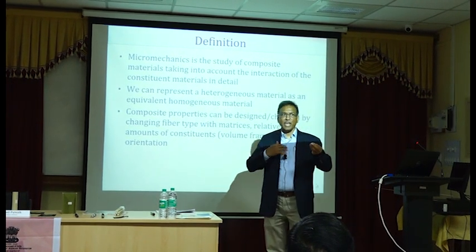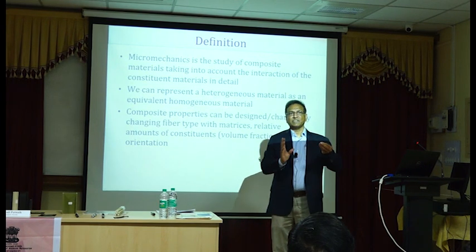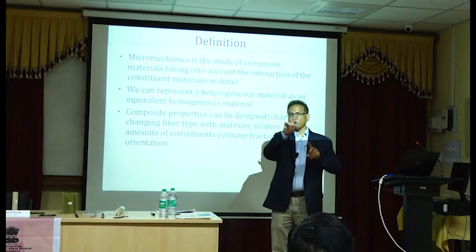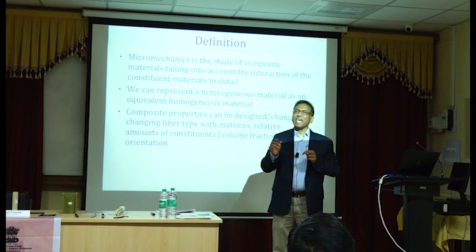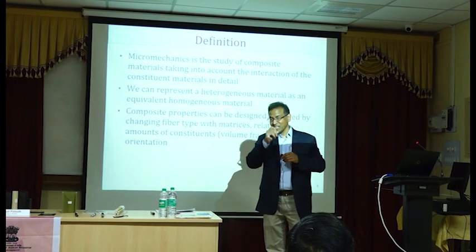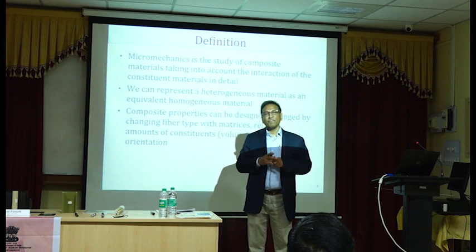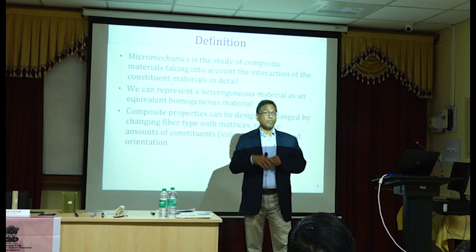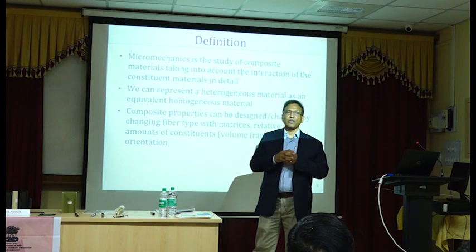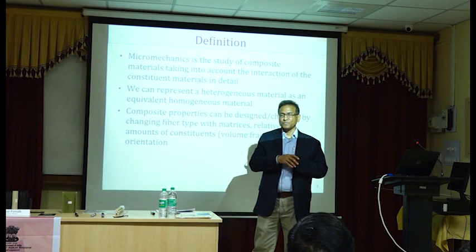However, we would like to maximize the amount of fiber in the cross section, so we would gain strength. Does that make sense? But you can go only up to a certain amount, because typically 50 to 55% by volume is considered to be normal. 60% is slightly high volume.